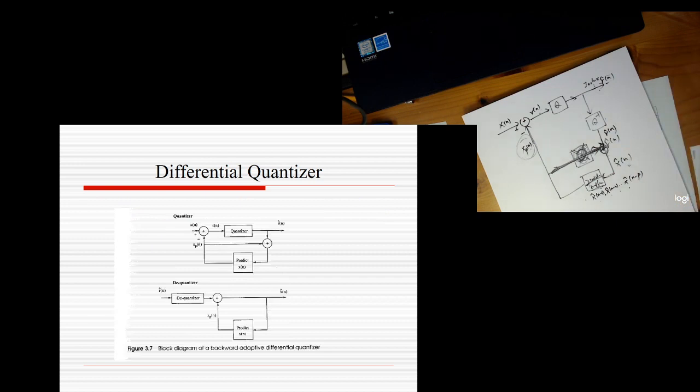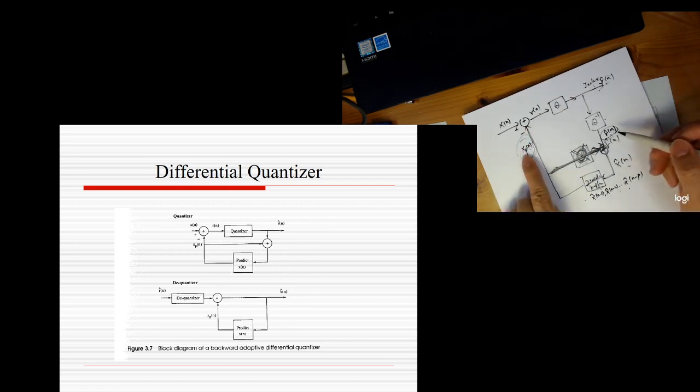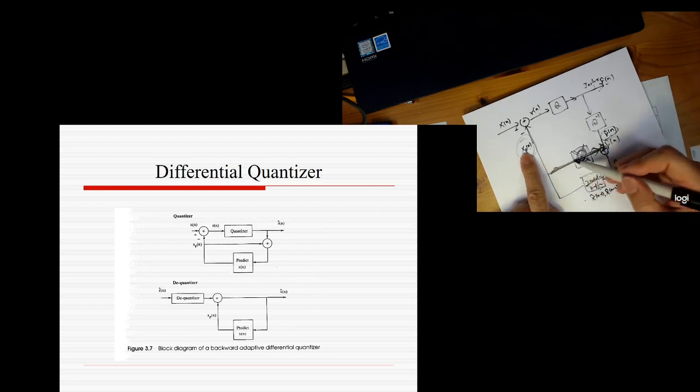In your textbook, sometimes the reader gets confused. What goes through the channel is not a quantized residual value. What goes through the channel is an index, just the index encoding bits. So you have to dequantize it to become the quantization residue. So the quantization residue is up here, and we have to add it back. We add our subtraction value back to become the dequantized signal.